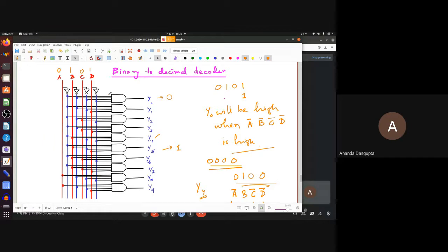Not to the others. Now, here, there's a bit of convention involved. The point is, when you are dealing with binary circuits or Boolean circuits, the standard convention is if two wires just cross, like for example, this wire has crossed here. You can see my pointer, I hope. And then this wire has crossed here. This wire has crossed here. If they just cross, and you have no special symbol drawn at the junction, you are just assuming that the two wires are not joined together. They're not connected. The reason why I'm saying this is when you draw analog circuits, usually the convention is this.